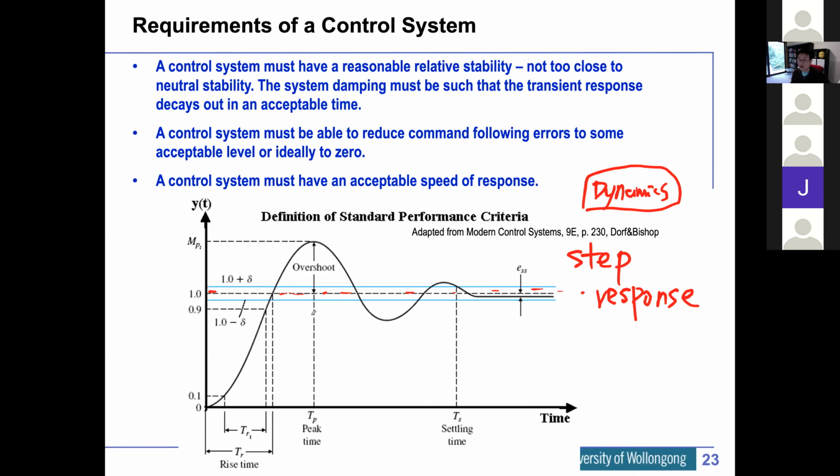You can use a hammer, just hit the structure with impact, or you can shake the structure, then you have an accelerometer to measure the signal. It will be something like that, okay? Or it will be like that. But that's not a step response, that's an impulse response.